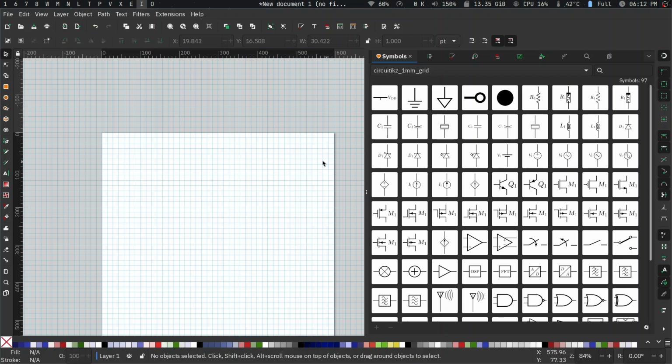So let's do a single 5 transistor OTA, which is very simple. As you can see here, I have a huge number of different types of MOSFETs, because if all you care about is using MOSFETs as switches, then this one makes sense. If you use MOSFETs as the typical ones that you find in analog circuits, use this one. If you care about showing what the bulk is doing, you'll have this one. Anyway, let's choose the one that people usually see in analog circuits. A 5 transistor OTA basically means two NMOS down, 2 PMOS at the top in current mirror configuration, and 1 tail current at the bottom, and that's it.